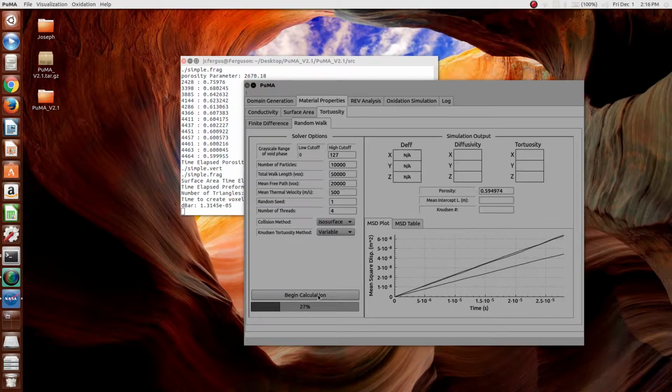The slope of this line is what is eventually used to compute the tortuosity, meaning that for the simulation to be converged, this should be a completely straight line. Often, though, it may look straight but not quite be, so it helps sometimes to take the raw data and process it in Excel or something in order to make sure that it's actually linear. When the final value is taken, it will neglect the first half of the simulation and only use the data from the second half of the simulation so that there's less error caused by the solution not being quite converged.